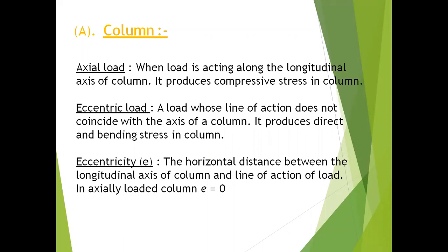Can you tell me any other real applications where those members are subjected to compression? Anyone? Pedestal, sir. Pedestal. It is provided as a base to the column. See, that is a bearing. We provide bearings on the top of the column to transfer load from the superstructure to the substructure. That is also a compression member. Struts, sir, struts. Very good. A strut is a compression member, which is subjected to compression force.